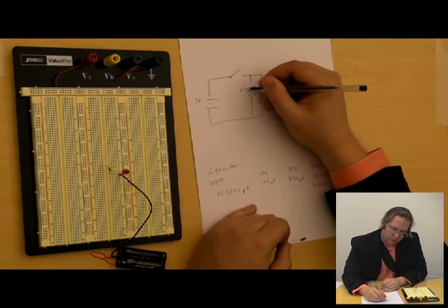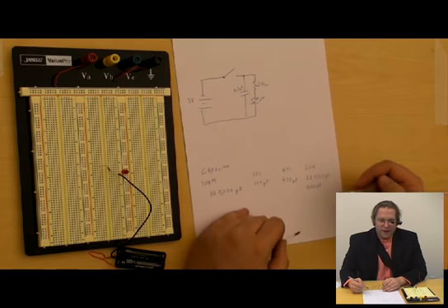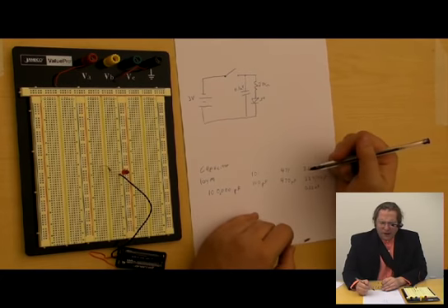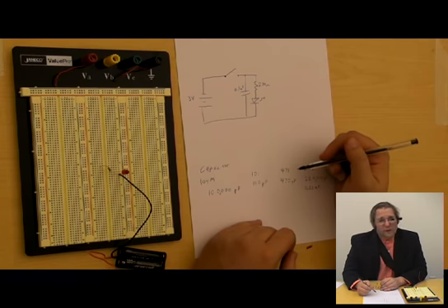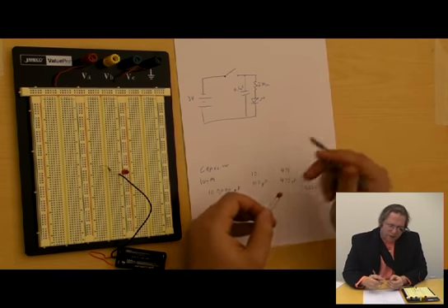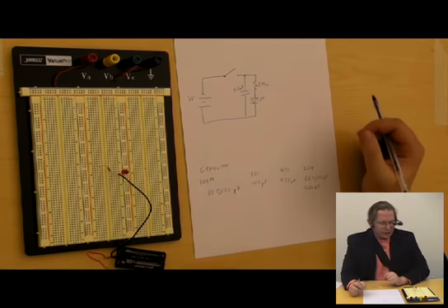And in this case, I'm going to write it down as 0.1 microfarads. So if I saw this on my diagram, I have to think about, okay, 0.1 microfarads is equivalent to 100,000 picofarads, and that would be 10 with 4 zeros behind it. Okay, so it would be 104, which is what I have. Now how do I change my circuit to look like this?